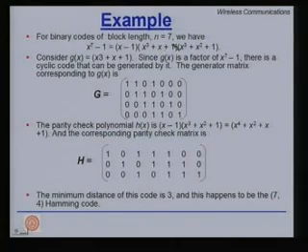So, for binary code, if you designate x cubed plus x plus 1 as our generator polynomial, then based on that we can write the generator matrix, and whatever is remaining, that is the product of the other two, will represent your h of x, which is given by x raised to the 4 plus x squared plus x plus 1, and the corresponding H matrix, the parity check matrix, is given by the following. We also made an observation that this happens to be the 7,4 Hamming code. So, Hamming code is also a cyclic code.